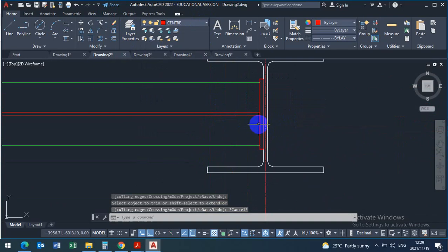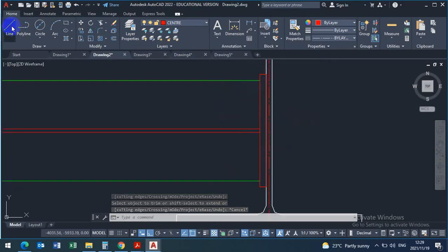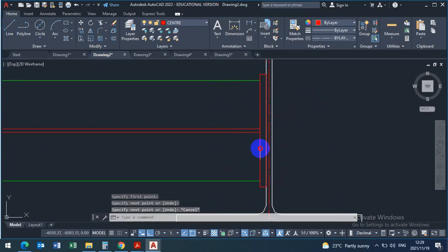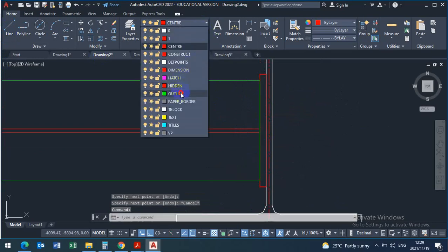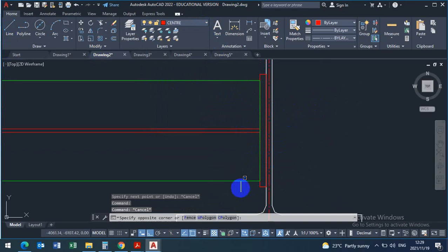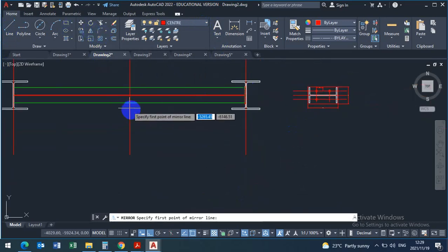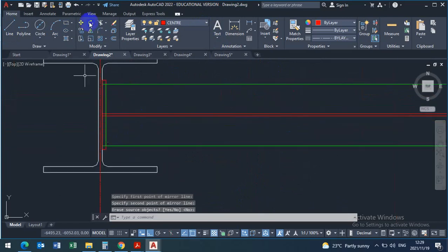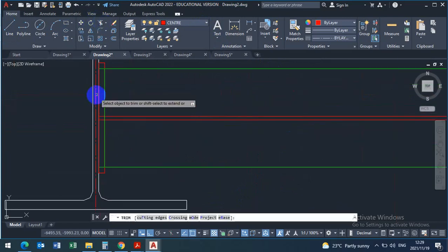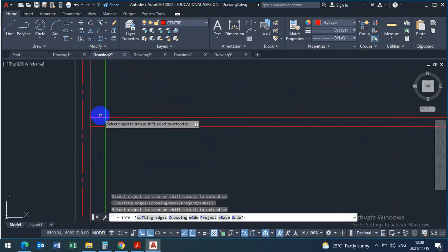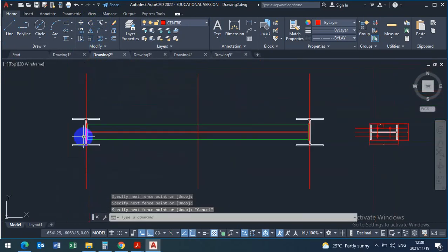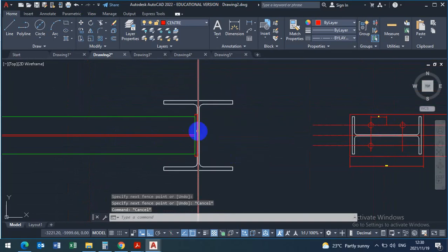So this is the green part. The beam will have a line here to here, and this line for the beam is outer line. Then you can mirror this end plate to the other side, because it's the same, mirror in the center here to there, enter, and then you trim the beam. Yeah, now we can project the hole positions here now on the thickness.